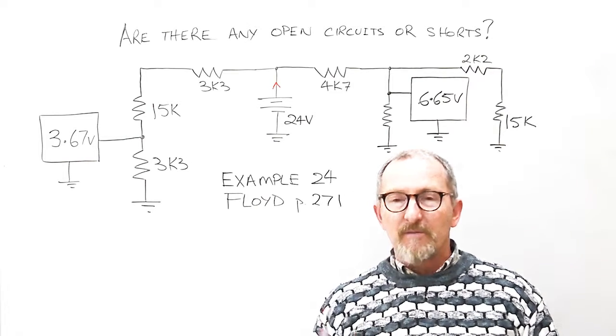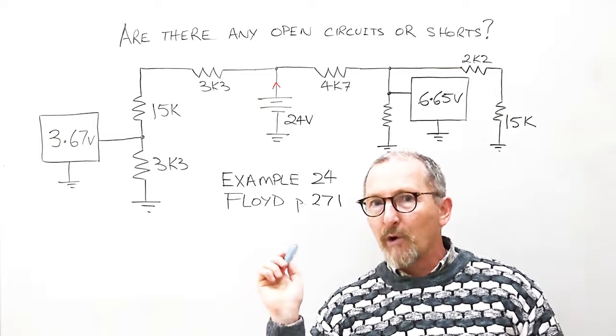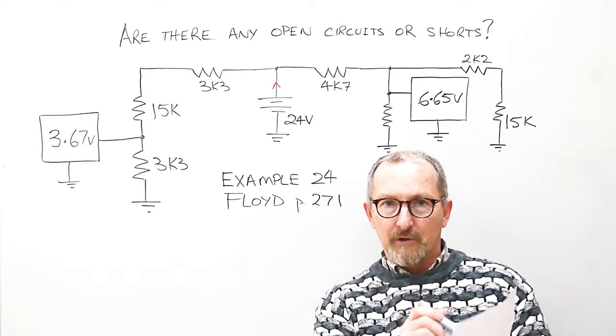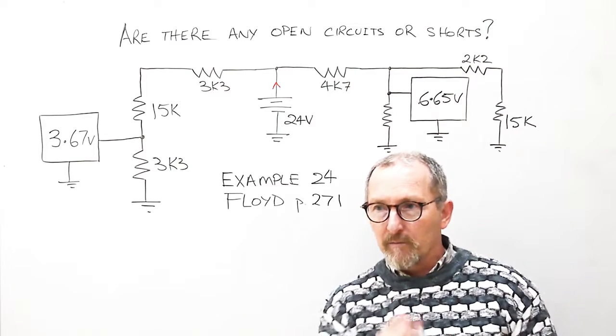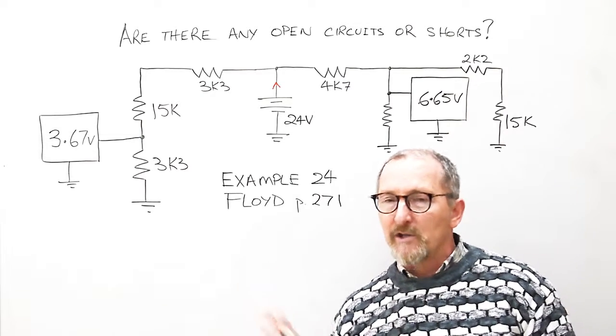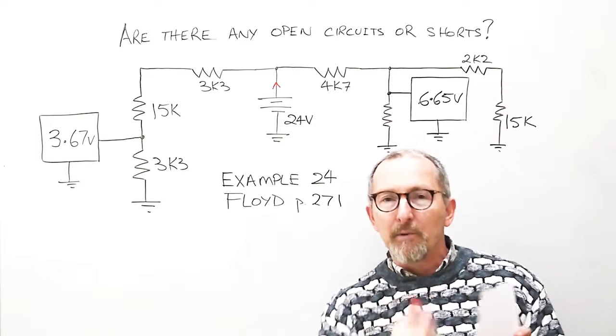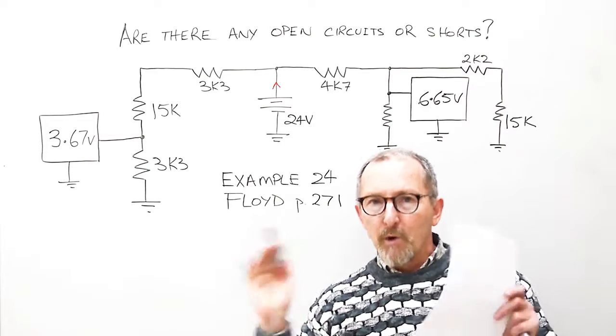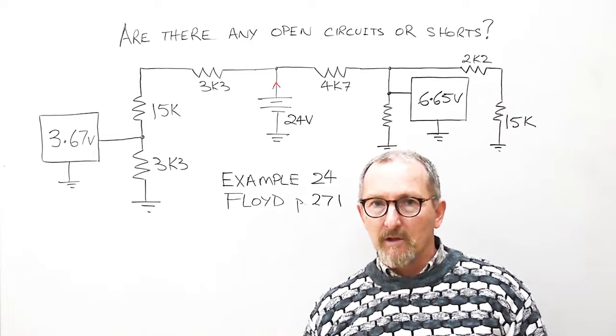And also, if you do the circuit approximations first, then when you do want to take out your toy, your calculator, and press buttons on it, if it doesn't match up with the approximation, you know that you've probably made an input mistake on your toy. So always think about what ballpark you should be in with a question like this.